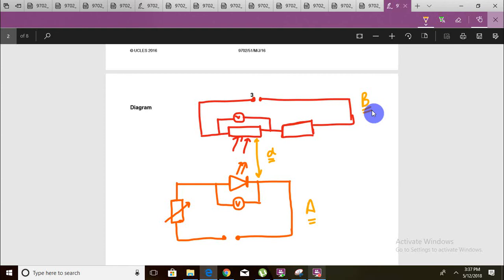across the LDR. LDR has a very high resistance in the dark and low resistance in the light. A particular value of the voltage will be decided to correspond to the moment the LED was emitting light of a particular minimum intensity, which would be seen as it being on. Stop decreasing the rheostat the moment that voltage is registered, and note down the voltage across the LED.